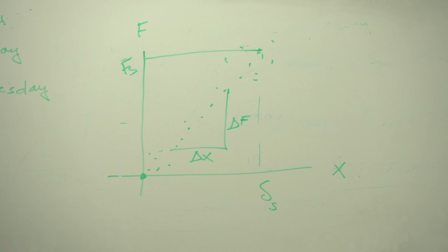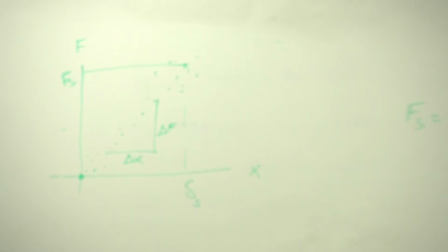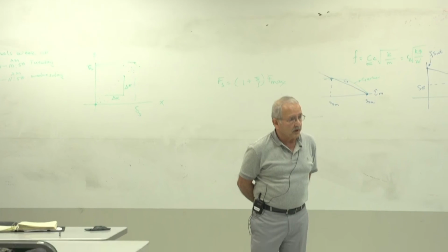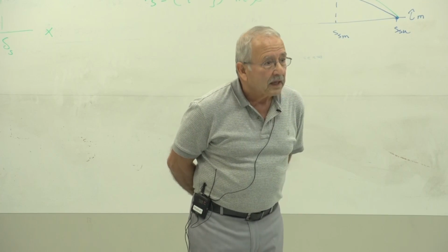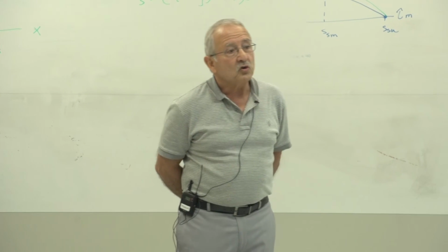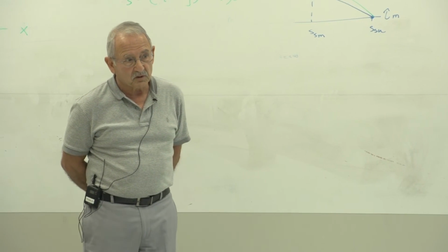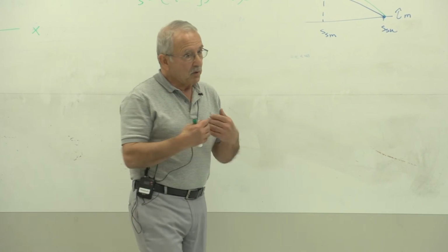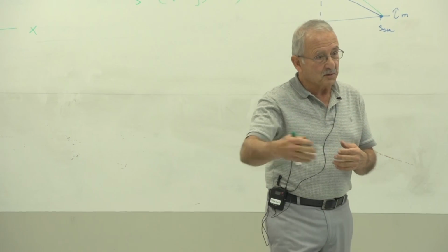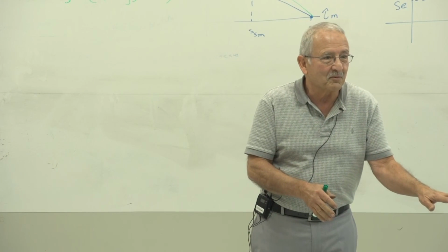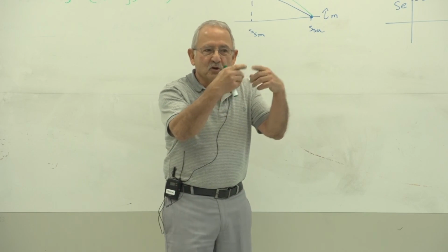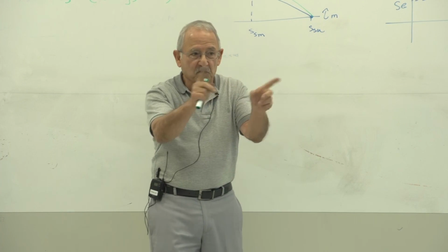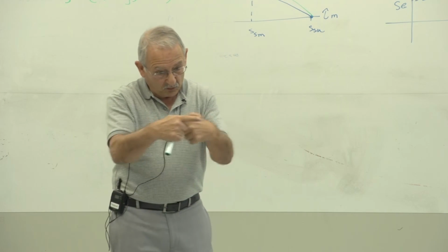And remember that if you use a large factor of safety, and you do that by increasing the wire diameter, then you're going to increase the weight. And if you increase the weight, you decrease the natural frequency of the spring, whereby we want it to be 15 to 20 times that of the applied load. Now you're going to reduce it to something less than that. So the two do not go in the same direction. So just having a larger factor of safety doesn't mean surge is not going to occur. In fact, they go in the opposite direction.